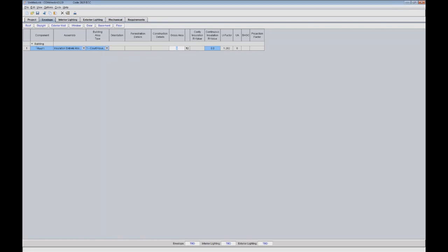So if I'm insulating at the roof deck, then I'm taking the roof plane and calculating out the roof plane for my square footage here. So I'm just going to enter some square footage and tab over. Since I did insulation entirely above the roof deck, it's already grayed out the cavity column. I don't have cavity insulation based upon this assembly type that I've entered.